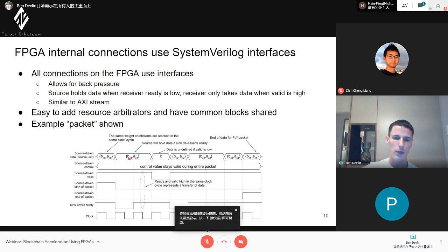And we don't want to have one big wide bus, so what we do is stack the coefficients. For example, if we're doing an addition of 2 elements, this is the first coefficients of A and B, and we send it this way. This also lets us make the design very scalable. You could have different size extension fields or different curves, and you don't blow up the resources on the FPGA.